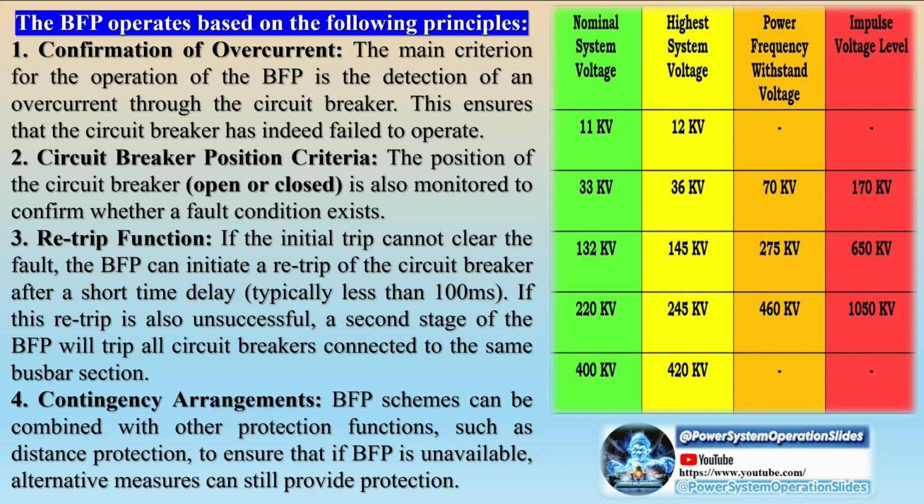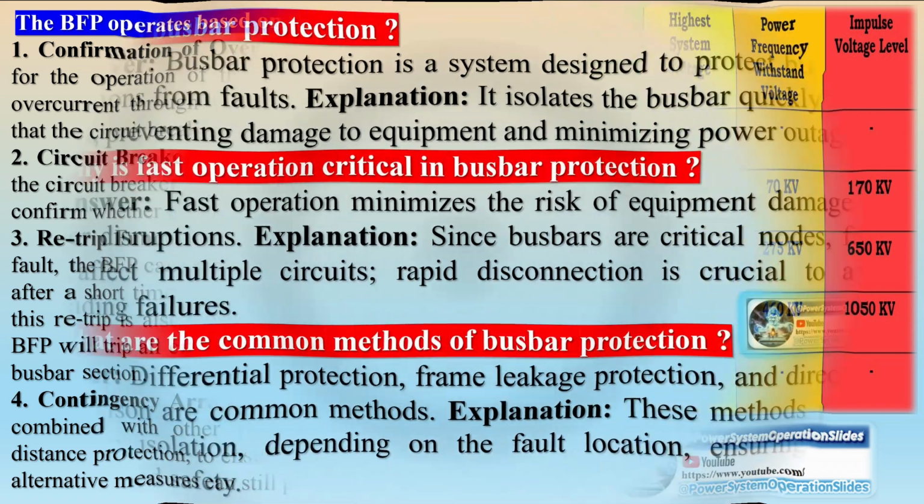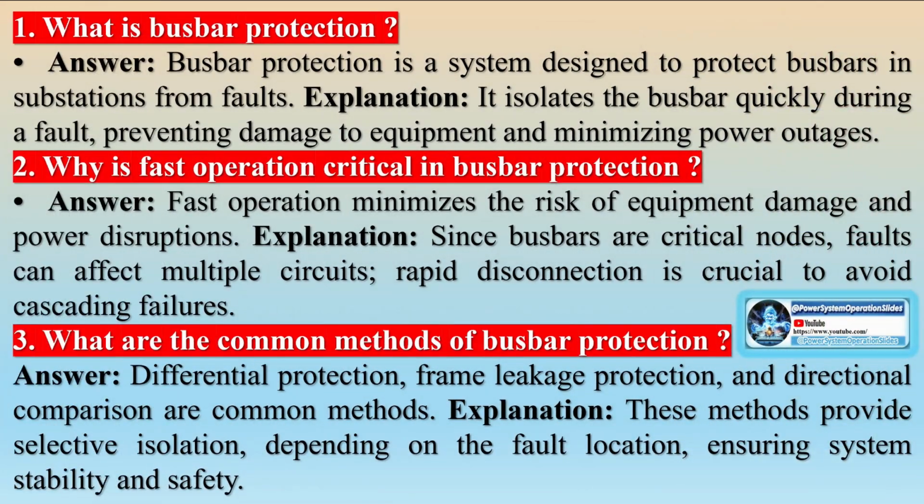Selectivity here means tripping the minimum number of bays necessary, typically those from a specific busbar section or system. Several types of CBF protection schemes are detailed in IEEE Std C37.119-2016. The simplest scheme relies on two signals within a specified time frame, an external start and an overcurrent condition, or CB contact information, or both. The external start is usually triggered by a trip command to the circuit breaker from any protection function.